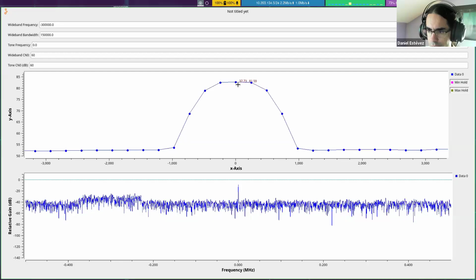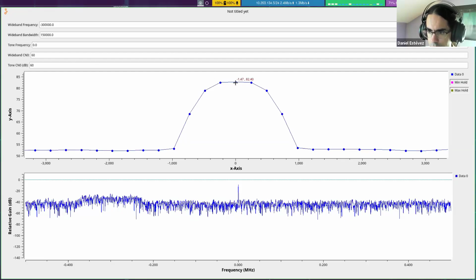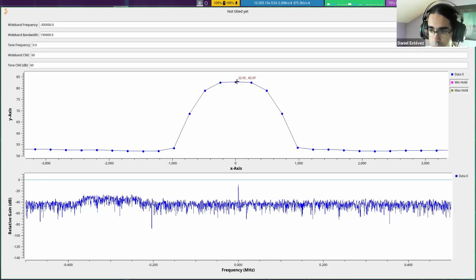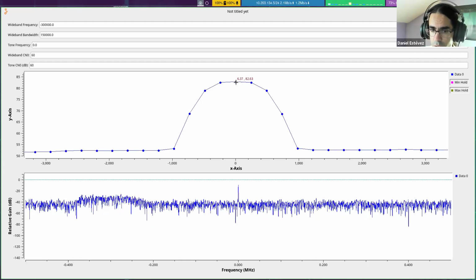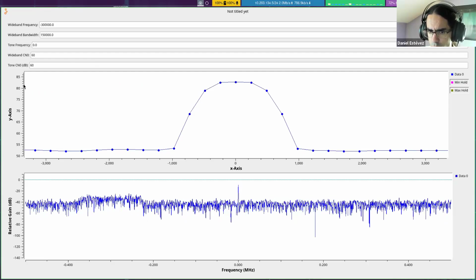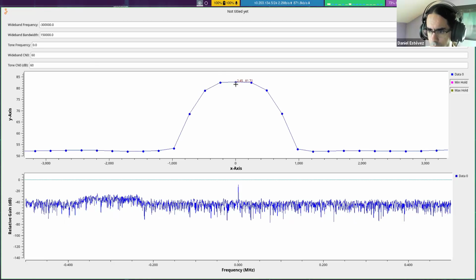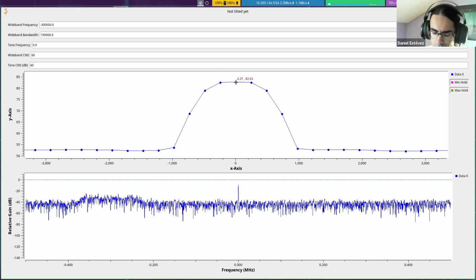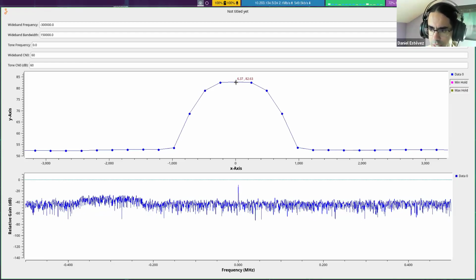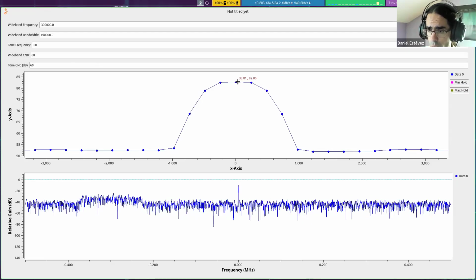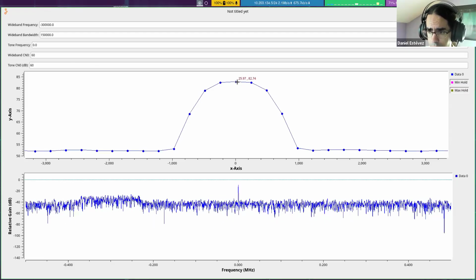So when the signal is centered at 0, it's centered on this bin. We can see the power is 82. It's not the same power as before, and that's what I told you. Do not make much use of these absolute numbers. They are only good relative. If you want to make use of them as absolute values, you need to understand exactly how the window scales things, how the FFT is scaling things, and oftentimes it's not necessary to go through that.